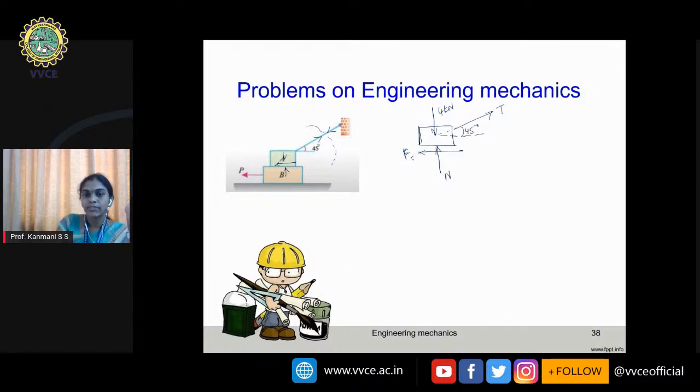So we know that F is equal to mu times N, or F is equal to 0.2 times N. This is the F value we have. Keeping these three forces, all that I need is to find the tension T. Let me find tension T. Firstly, let me apply the first equation, summation Fx equal to 0, rightward force is positive.